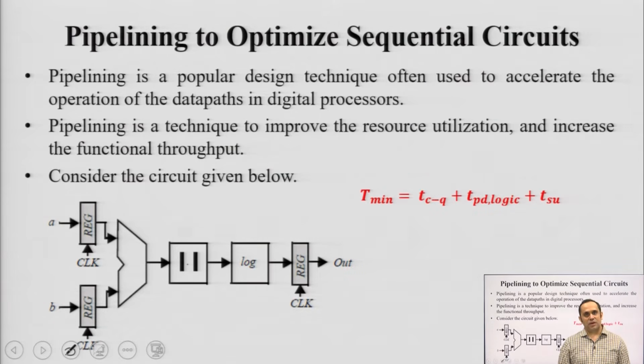That has a lot of advantages in terms of implementation, and understanding it is quite simple, but as the size and the functionality requirements increase, from the performance point of view, every CMOS circuit is analyzed in two parameters. One is known as delay, another is known as power consumption.